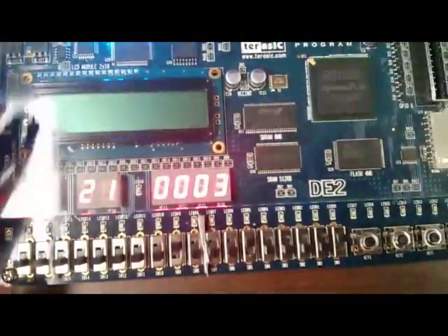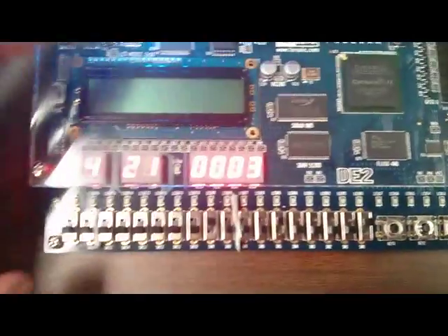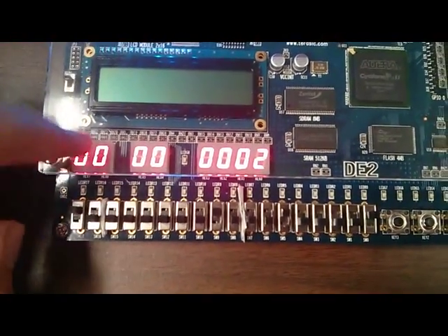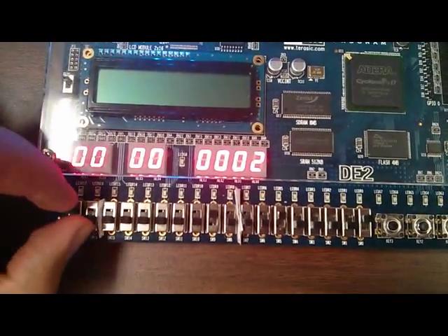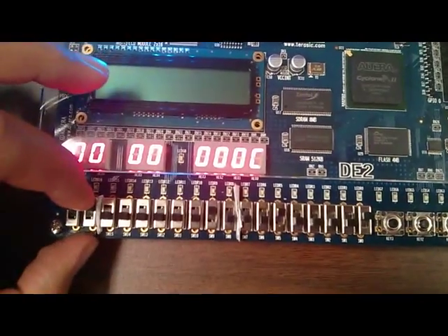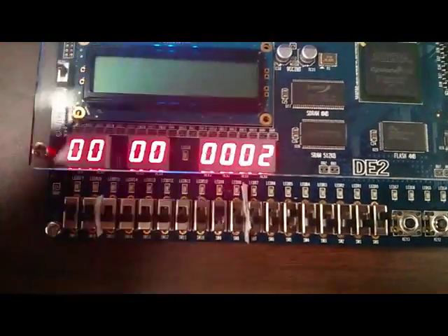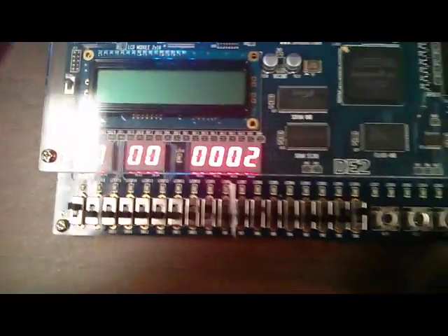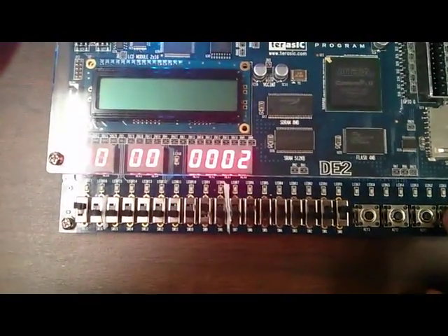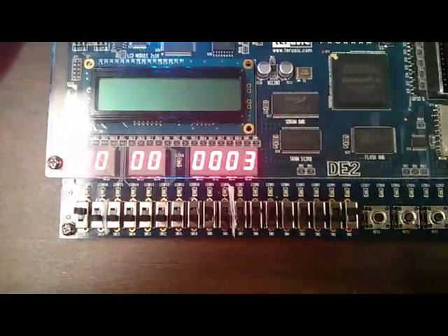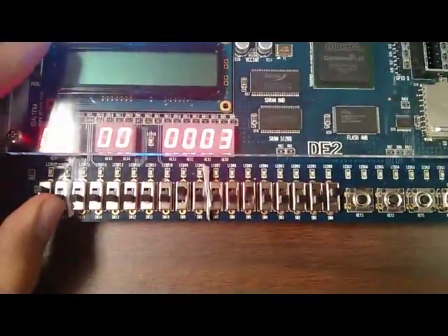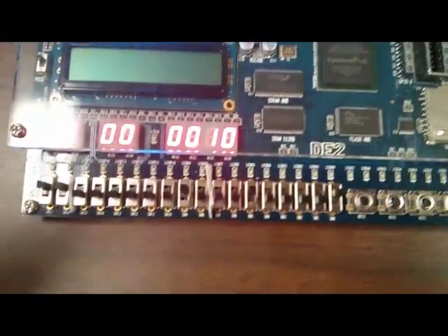That is the instruction. After pushing my clock cycle button, output of the ALU should be 3. My program counter should become 10 or 16, in decimal that is. Push this button. Expected output, that's 3. And 10.